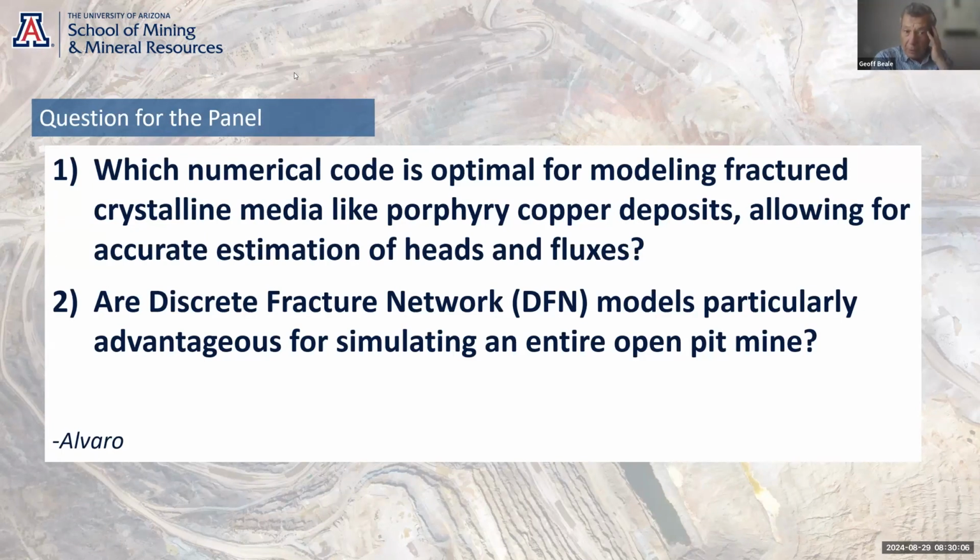And so a DFN model typically assumes that types of fractures, fracture orientations, and fracture depths are homogeneous or consistent. And as we see in the course, for any fracture, the properties of that fracture are very variable on a scale of a foot, 10 feet, 100 feet.